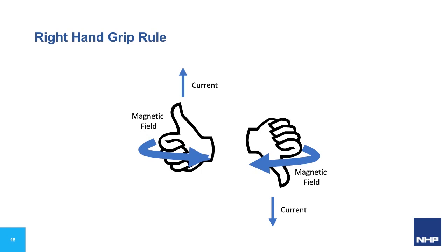So think of the flux direction, force acceleration and deceleration as you would observing, say, a top-loader washing machine agitator. Imagine two machines side by side, the central spindles being the conductors. And if we place two conductors carrying the same source of current next to each other, but the current directions oppose each other, the magnetic flux forces will also oppose each other with forces that proportionally correspond to the value of the current at any given time point on the current sine wave.